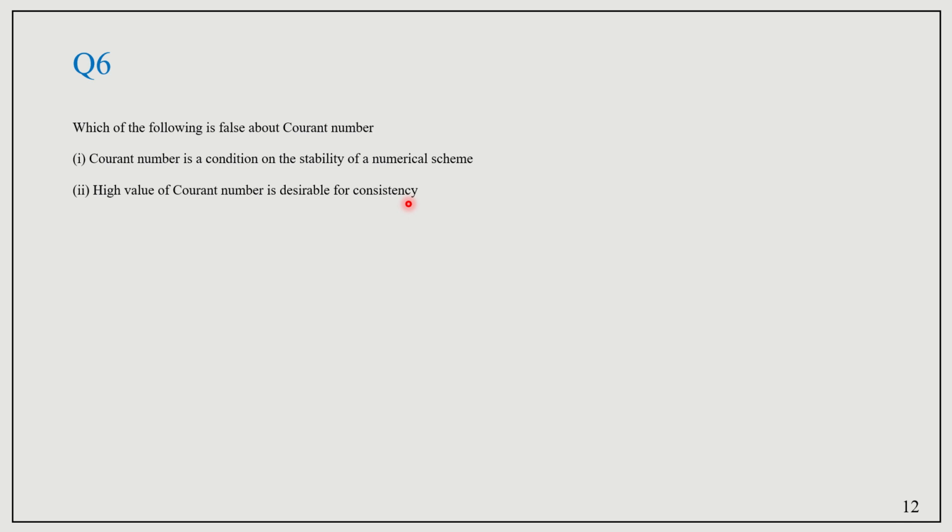the solutions will diverge actually and we will not get the solution. It will be very high. It will lead to very unrealistic values if Courant number is very much higher. And also if this will be the case, that is velocity keeps on increasing, when Courant number criteria cannot be met, the solutions will diverge.